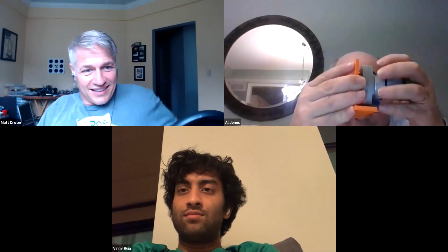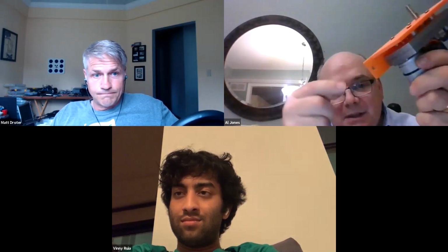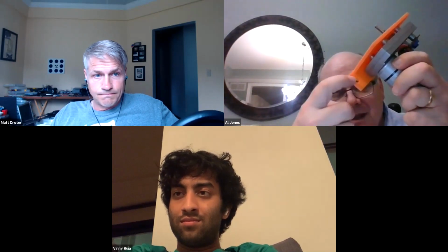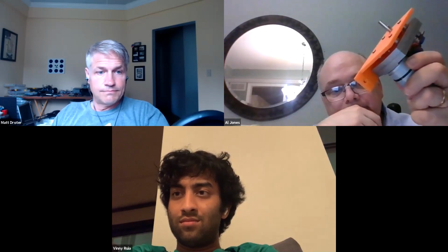For the actual cover, I had no problem with that being plastic, but for the structural piece, I think you're going to be happier with metal. We do the design so you can take it to a fabricator and say, make this out of metal. We can try it and see how much it will withstand, but 80 pounds, that's a lot of torque. I would just be worried about there being a stress point where it's connecting.